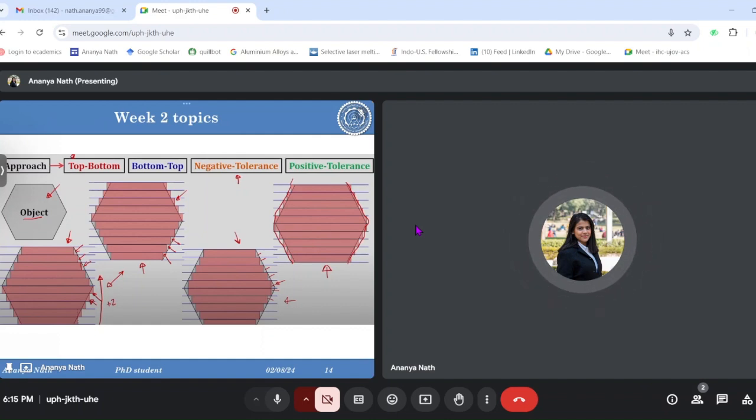For negative tolerance, a lesser amount of material is getting deposited, so after machining there will be lesser dimension than the actual dimension in the object. And again, the object dimension can be exactly achieved by depositing it with positive tolerance, but again the material wastage will be more in this case. So these are some approaches by which you can get different types of deposition pattern with indirect type of slicing. This knowledge can be used to minimize the support also.